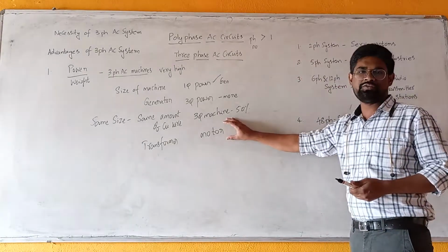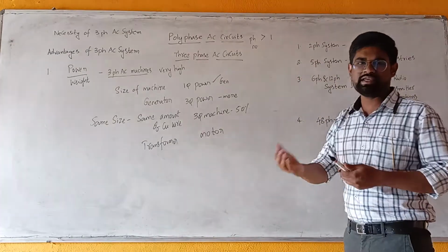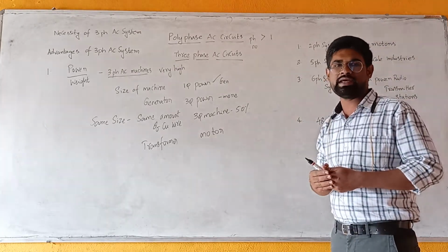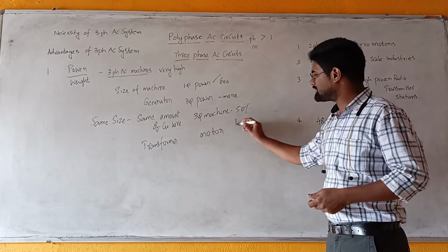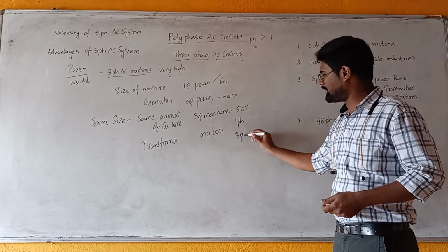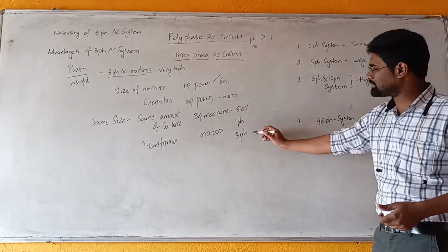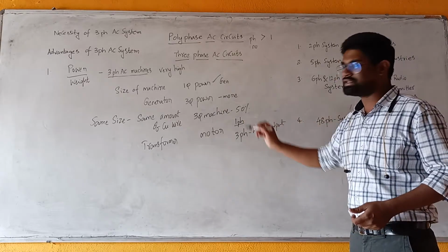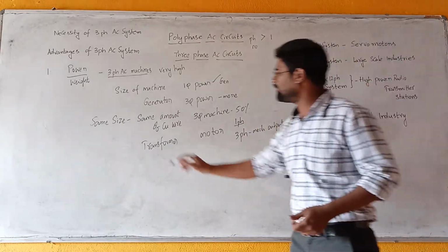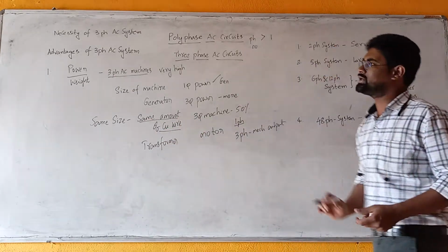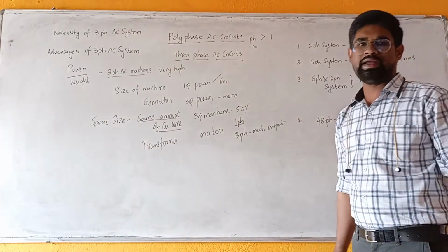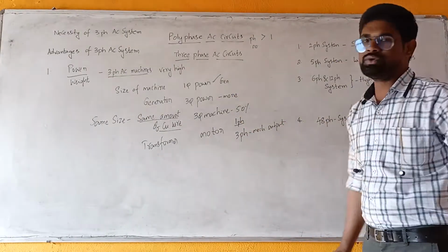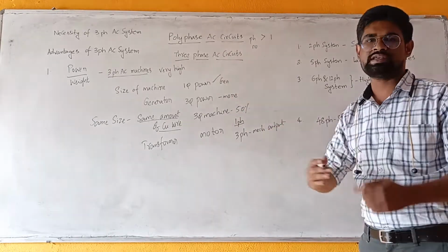Similarly, comparing three-phase and single-phase motors, a three-phase motor gives more mechanical output power for the same amount of copper wire used in the motor. So this is one of the fundamental points why we go for three-phase AC systems: the power to weight ratio of three-phase AC machines is very high.